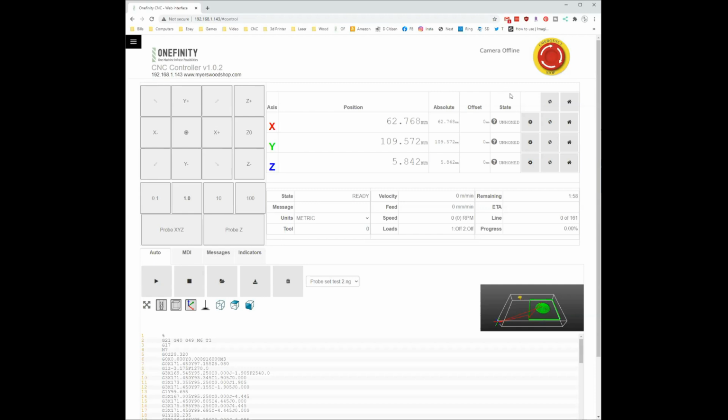But for the machine to know where it is, you have to hit this little home. I'm pointing to the screen like you can see that. You have to hit the home button. We can see your mouse also. Oh, okay. Yeah, you have to hit the home button here. So when you hit this button, the machine will home itself. It'll move itself to the extremes on the front left and the highest on the Z. And once it does that, it'll be like, okay, this is how far I can travel. Because if you don't do that, it's going to try to run off the rail and just go forever because it doesn't know its limits.